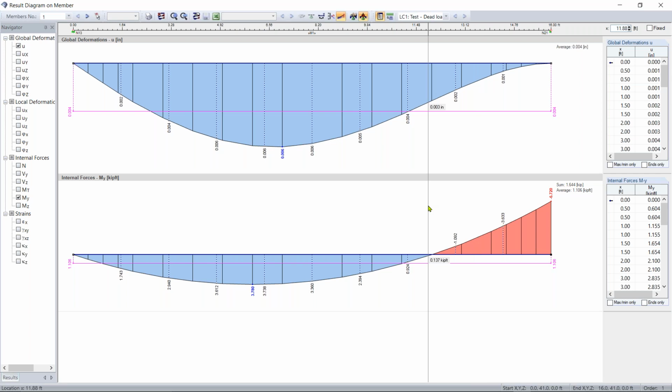I'm just reading the question one more time. Yeah, I think it's just inflection points. You can see within this results diagram the distance up at the top. Oh, he or she wants to know it for the plates. It's exactly the same thing for a results diagram. You can do it either for a member like this or for the section cut that Alex had made through the continuous plates. You can also view a result diagram in this exact same manner, by just right clicking on it. Inflection points, this will give you more details on those diagrams.